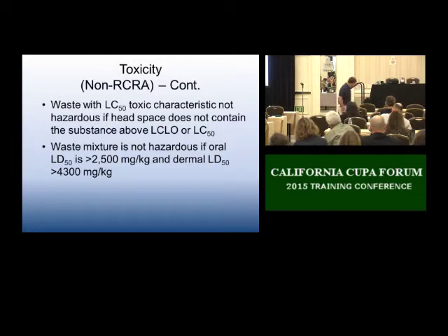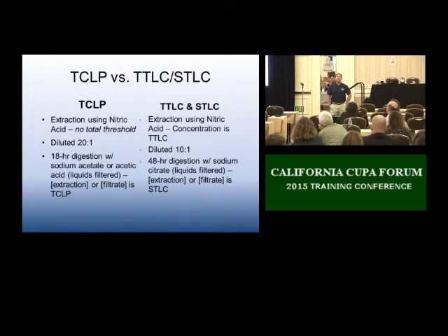Okay, here we go. The first one listed is ignitable. A waste is considered to be ignitable if I take my waste and test the free liquid, i.e. it's a liquid, and I use a Pensky-Martens closed cup test methodology, give it to a lab, and they determine that the flash point of the liquid is at or below 60 degrees Celsius, which is 140 degrees Fahrenheit. If it's at or below that threshold, and I decide to discard it, that is a federal and a state hazardous waste.